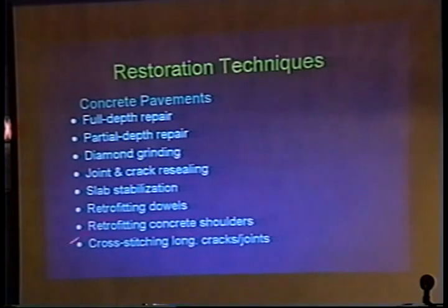Another technique for longitudinal cracks is cross-stitching. We put cross-stitching tie bars, drilled into the pavement and epoxied in at angles like that, to give you a cross-stitching effect.